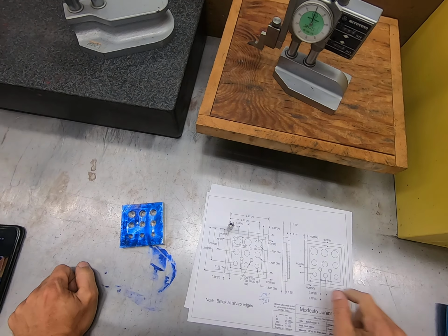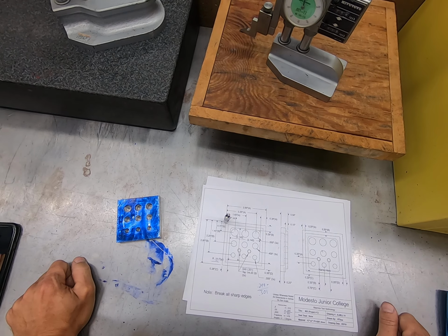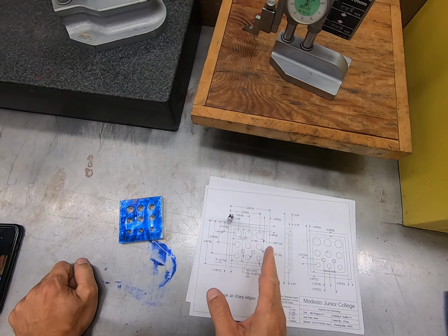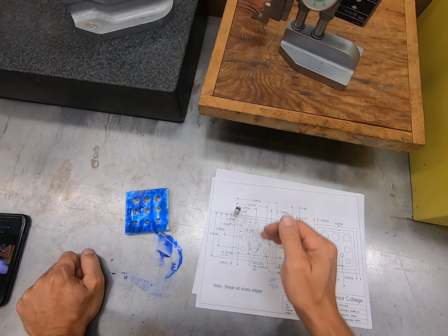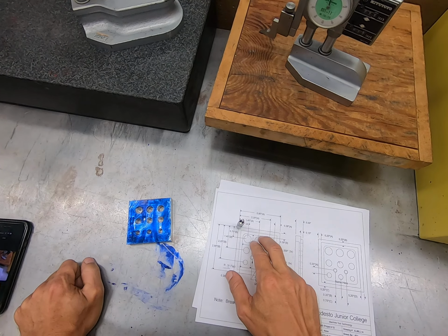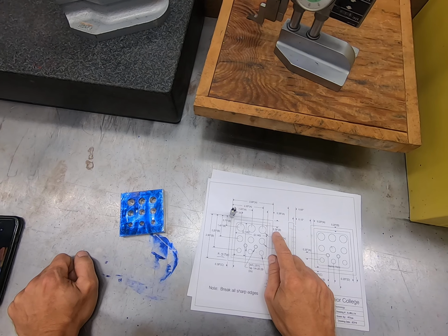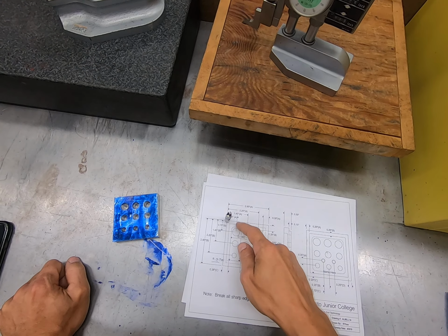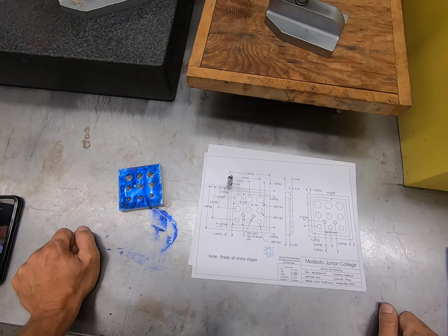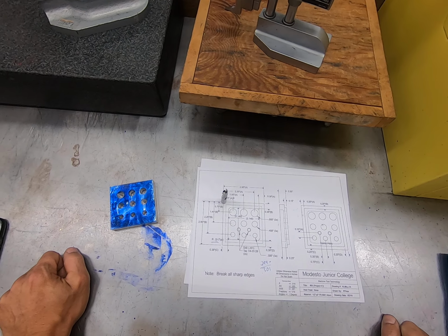So to get to this corner inside of here, I can't just use the drawing dimensions. I would have to compensate for the radius of the tool horizontally and vertically to get it into the right location. That means I'm adding some numbers onto the actual location that the blueprint shows, which is 380 thousandths. Well, then it gets weird because when I come down to this side, I'm actually going to be subtracting the radius off. And I'm probably confusing you already, so that's why I'm not going to demonstrate it being done that way.